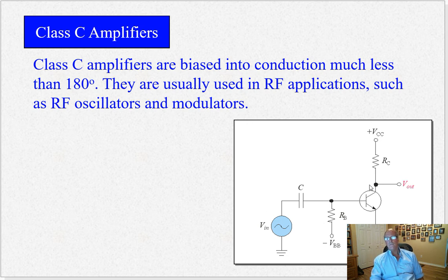So what's the power dissipation of a transistor when it's off? Well, it's zero, right? Because there's no current going through it. There's no power. Power is current times voltage. Well, if current is zero, you have zero power, okay? So that's when the transistor is off. So here comes the input waveform. It gets towards its peak, turns the transistor on just briefly, all the way on. So when you turn the transistor all the way on and it goes into saturation, VCE is zero. You have 0 volts, but you have full current. So 0 volts, again, times full current, you still have 0 power. So this transistor is living a pretty good life.